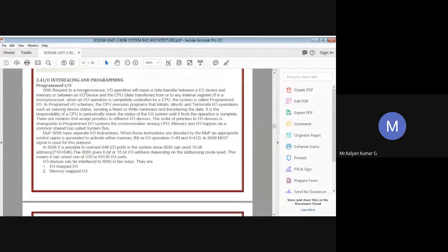Synchronous data transfer scheme is the simplest when compared to all the other data transfer schemes. In a synchronous data transfer, the processor does not check for the readiness of the device. The IO device or peripheral should have matching timing parameters. If so, the processor does not check the readiness of the device. Whenever data is to be obtained from the device or transferred to the device, the user program can issue a simple instruction at the device. At the end of this instruction execution the transfer would be completed. So this is a simple type.